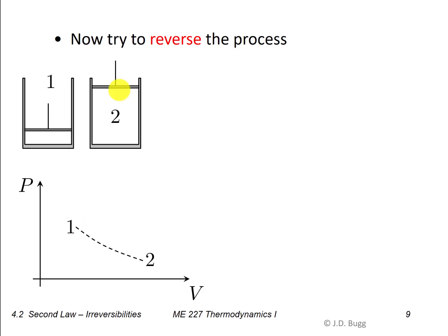So we're going to take this gas and compress it. We're going to reduce its volume to get back to point 1. So at point 3, the volume has returned back here, and we're part way along the process of reversing this process. We've been successful in getting the volume back to where it started. So that's an initial step at least. However, if we think about what happens to this gas as we recompress it to our original volume, we're going to have to move the piston from here to here.